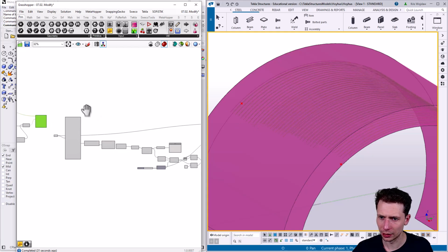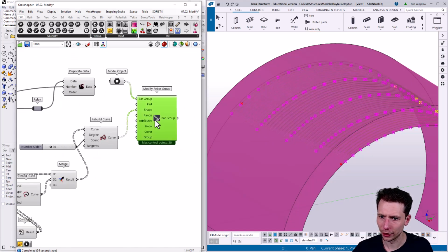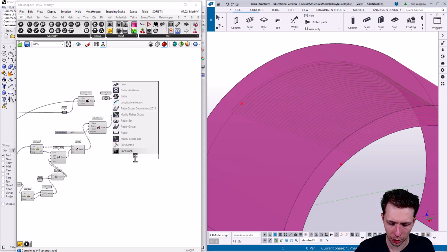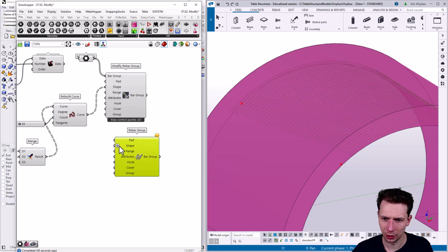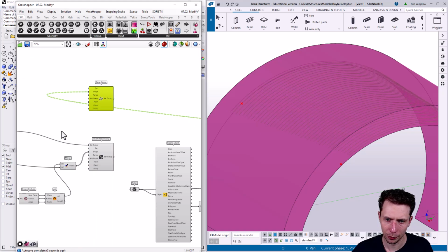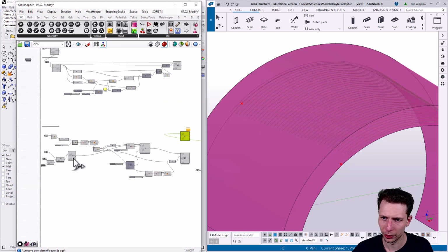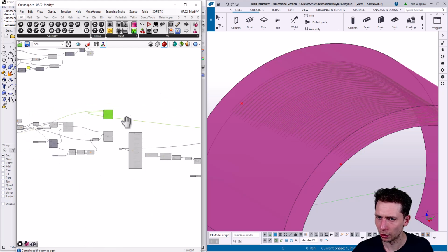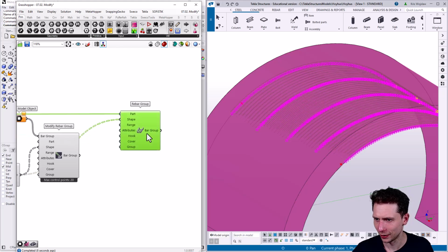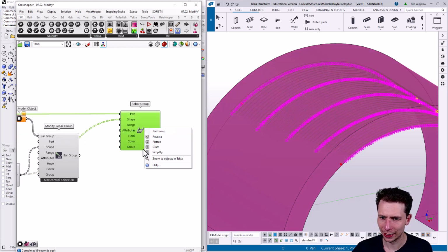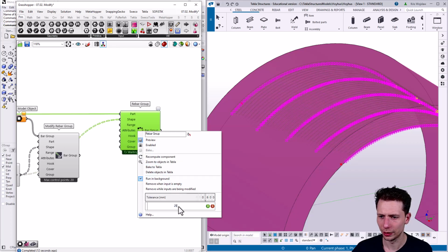Here I cheated just a little bit, but we can also try to just delete this one and delete this object. So we have all these groups, and we can try to just create just a rebar group. And now let's connect the shape, so it will be the same. Here will be the shape, and the part will be the same part that we modeled here. So if we model just once again, we will get 4 groups. So now we can see it, and let's change again the number of points, let's say to 25.